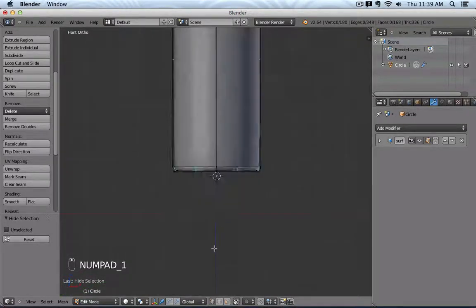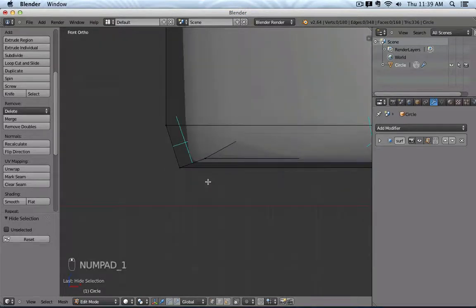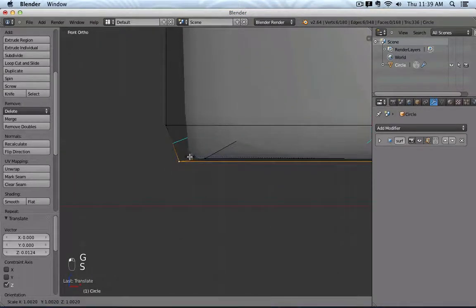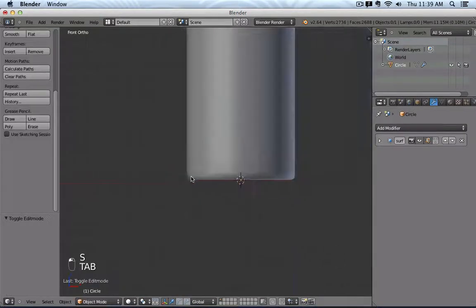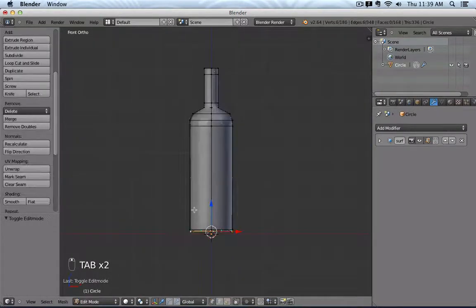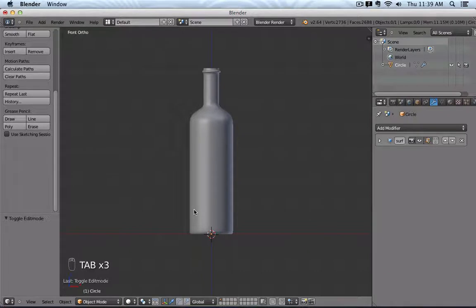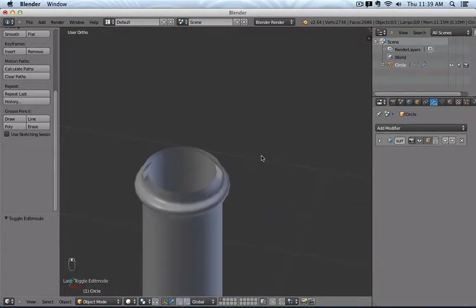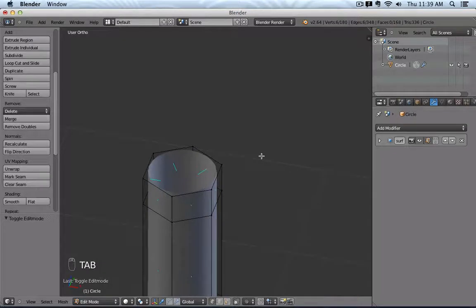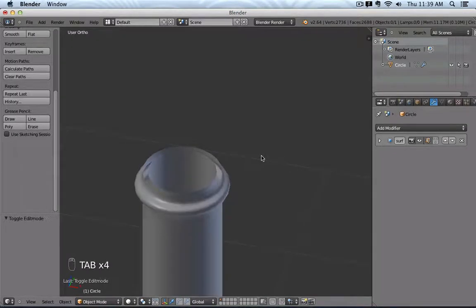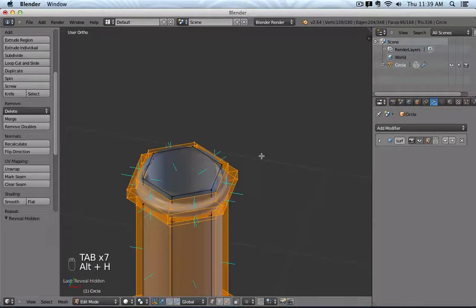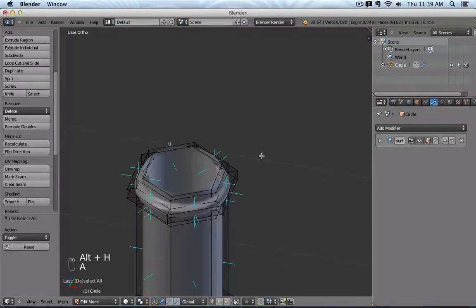This way, for example, it might be easier to do some final adjustments to the mesh. And then if you would like it to be visible again, you see also in object mode you will see the geometry. If you go into edit mode, then it's gone. So it's actually a really nice feature. And then you can press Alt H and it's all back.